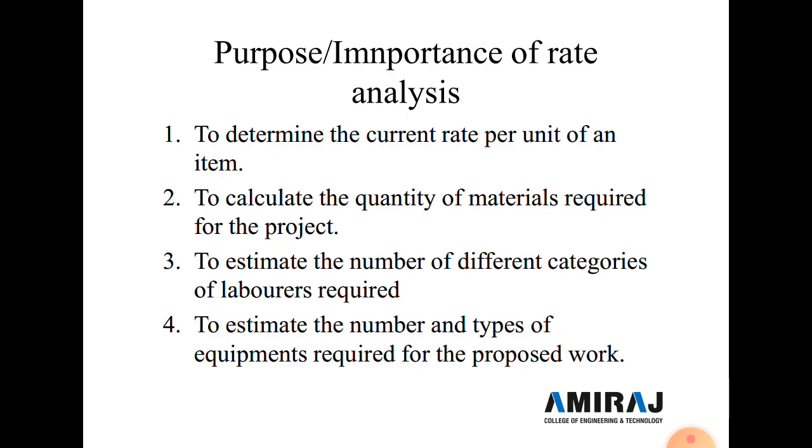Now we discuss the purpose and importance of rate analysis. Here, first, to determine the current rate per unit of an item. Second is to calculate the quantity of material required for the project or to complete any item of work. Third is to estimate the number and category of labor required.